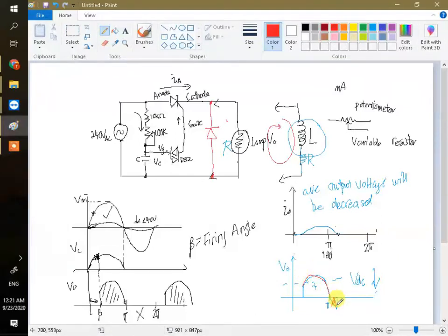There is no negative after you use what we call the freewheeling diode. This is really important. This is a really important component in power electronics. So if you don't know this, probably you should retake. I explained it a few times already. Just use one diode here, and you can take away this negative waveform.